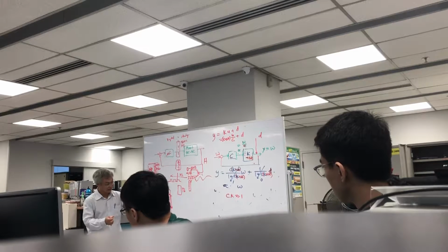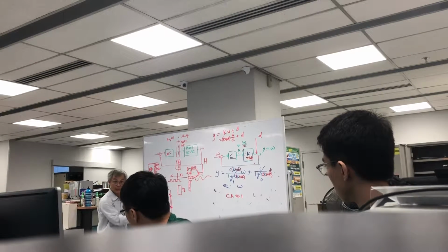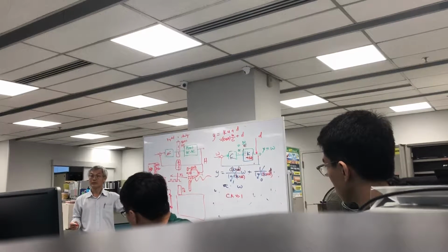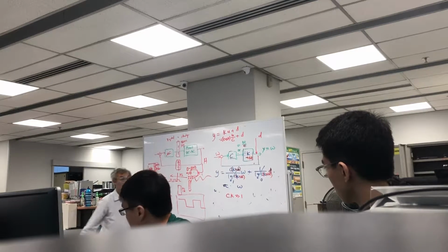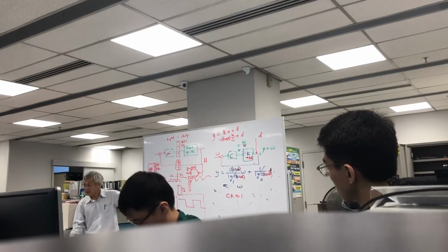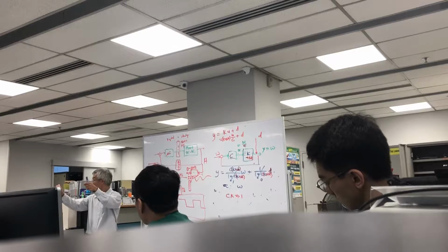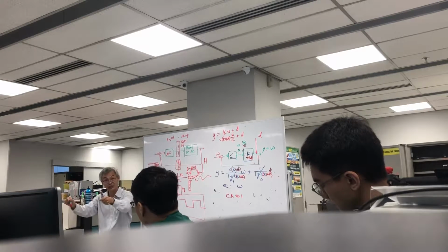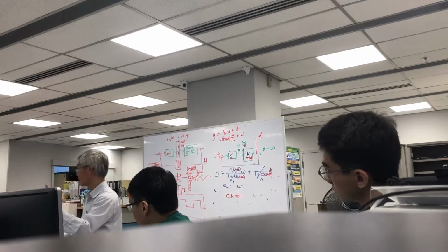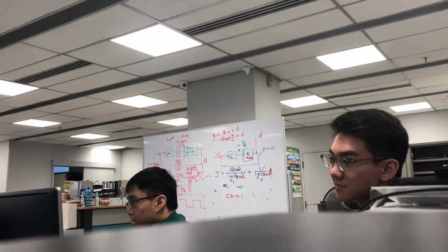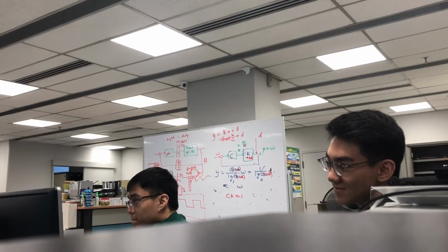So you have this and you run this, and because this is going round and round, what do you expect on your oscilloscope screen? If you monitor this pin, you will see high, low, high, low, high, low. Because it runs round and round, it gives you a periodic signal. You use the scope, it's very stable, and then you can take your time and measure. No need to read the manual, you know exactly what it is. This is one of the job interview questions. If you come to this, you can answer this. You can get a job.